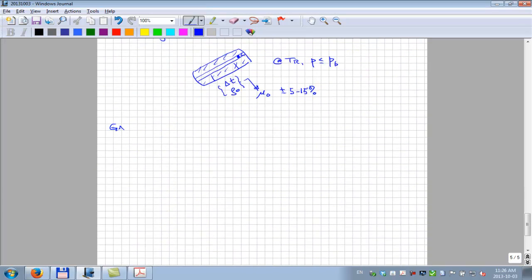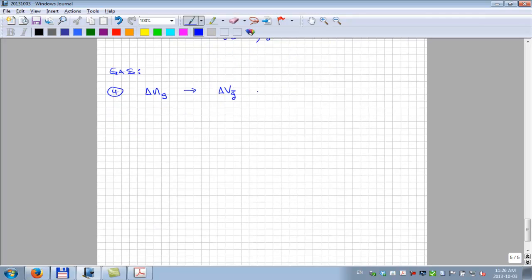So on the gas side, they have these moles of gas removed that probably will be converted, using 23.68, to a standard gas volume. And then what's actually reported, it'll be one of two things. It'll either be the incremental gas over the residual oil volume,